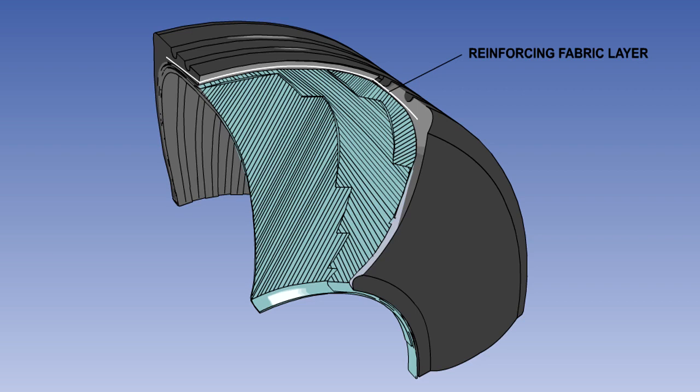For special high-speed applications, some tyres have a layer of fabric woven into the tread. These tyres will have reinforced tread printed on the sidewall. This fabric may become visible during normal wear. This is perfectly normal, and the tyre can continue in service with this layer visible.